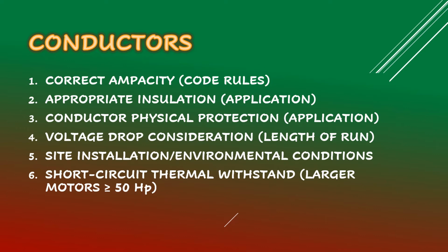By the rule, for a motor equal to or larger than 50 horsepower, we have to calculate the short circuit thermal withstand of the conductor, because during fault conditions the motor will contribute to the fault current. This is a very complicated calculation, so we will consider it in another lecture episode.